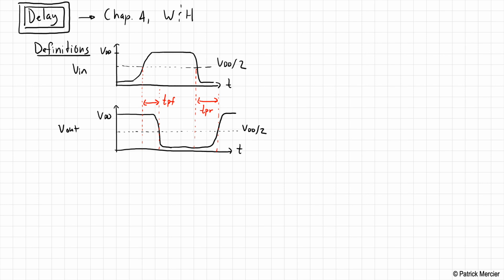Now, the reason we care about propagation delay and not so much for, you might think of delay as like rise time or fall time or something like this, and we can use different definitions for what rise and fall time might mean. Is it the rise time 0% or 10% of the signal to 90% or 20 to 80%? Something like this. Those are important and they do matter in certain circuits, but as we'll find in digital design, it turns out that it's the propagation delay.